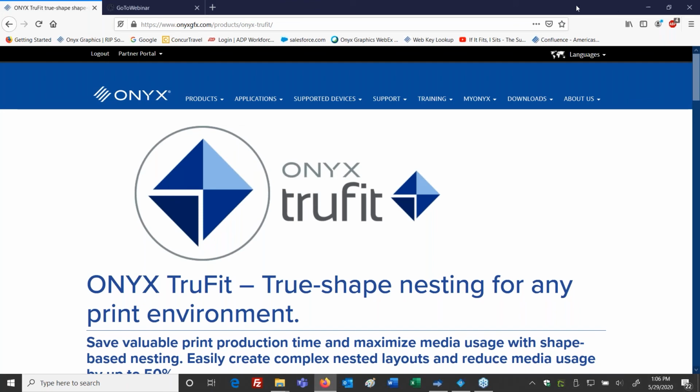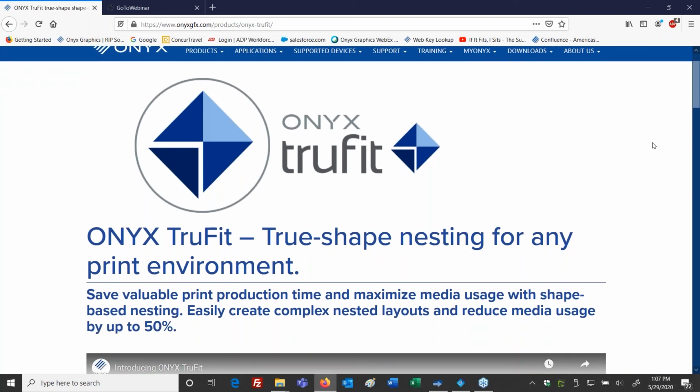So I want to talk to you guys today about ONYX TrueFit. ONYX TrueFit is a product we at ONYX Graphics worked in conjunction with a third-party development company to come up with. The goal for making this product was to give end users a tool that allowed them to shape-based nest. And the purpose of shape-based nesting is to save valuable print production time and to maximize media utilization. Now, with TrueFit, what we've been able to accomplish is we've been able to give users a way to reduce their media utilization by up to 50%.